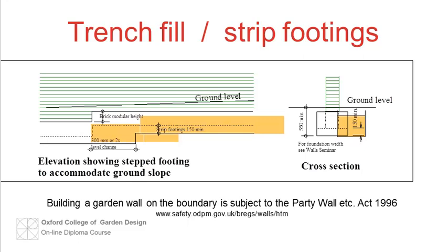Trench fill can give advantages of speed and economy, especially for deep foundations, by keeping the width of trench to a minimum. This is because the trench can be excavated by machine and filled with concrete to near ground level. Therefore, no one is required to work in the trench, either digging or laying bricks, and the trench width needs to be only as wide as structurally necessary to support the wall.